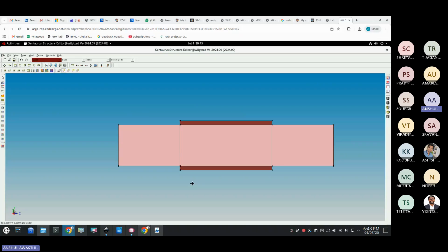Okay. So this is the oxide layer. Now I want to place the metal. Either you can place polysilicon or you can place metal, whatever you want. So I'll just place metal, aluminum, here. You can see there is polysilicon also.